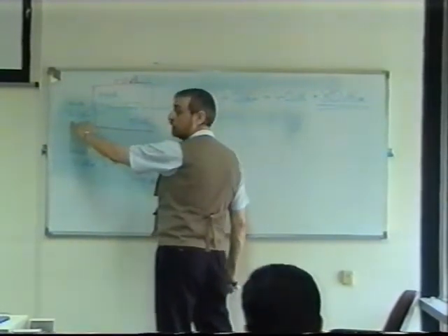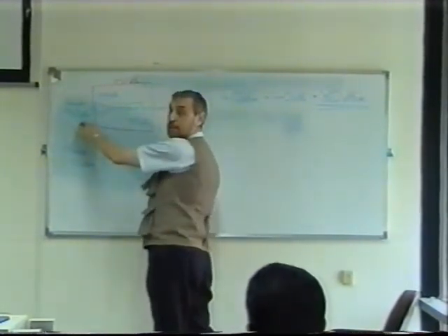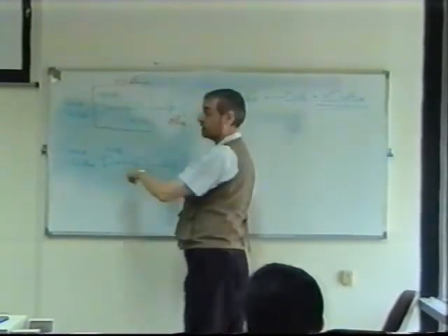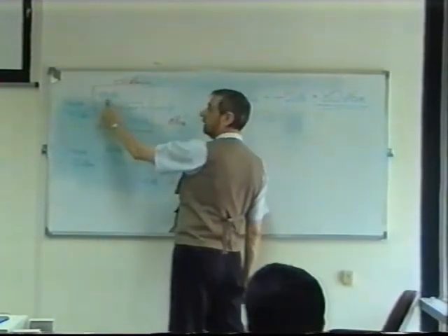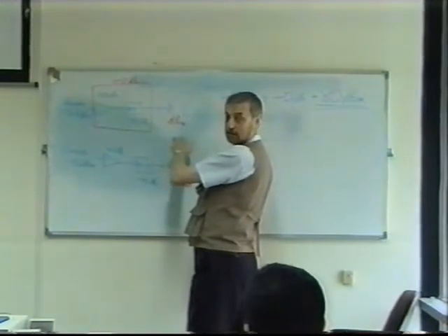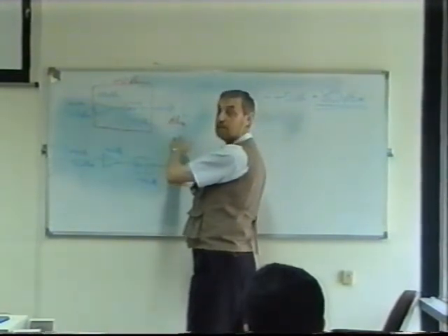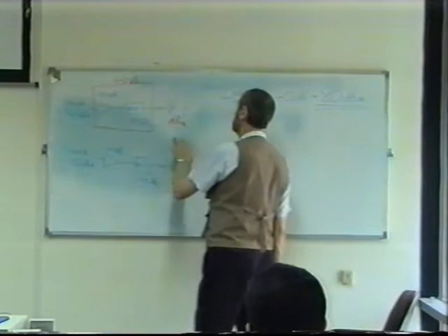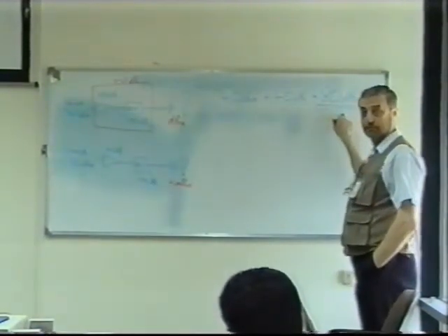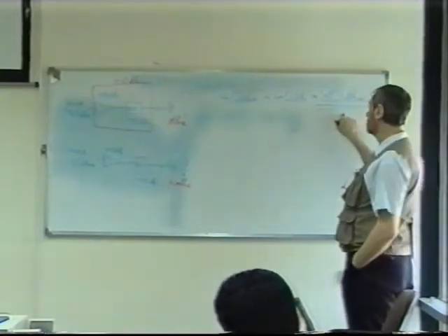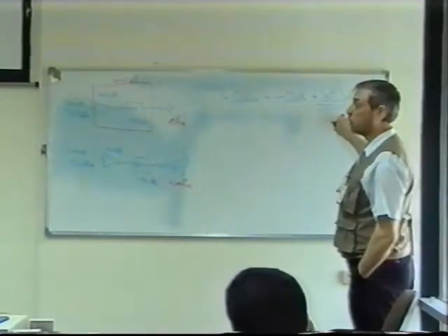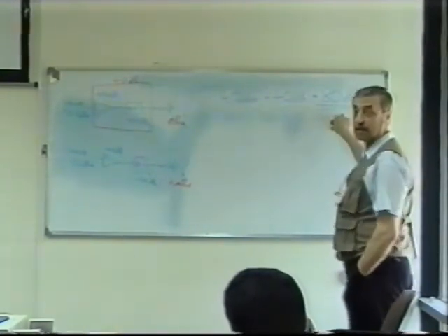So all you have to do, if you've already got your power in dBm, is just add the dBs or subtract the dBs, depending on what you're doing. So we begin with 40, add 100, minus 60, 80. Do you agree with that? In dBm. If it's in watts, you then can get the final output and change this to watts. Okay? No, if the power input is in watts, then it's a different calculation altogether, isn't it?